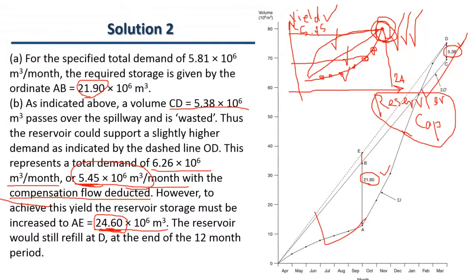On top of all of them, I'd like to give you another level of uncertainty that we have to deal with. That is the uncertainty of the inflow. You're not sure that the inflow that's going to happen is the one that was listed in that figure. Unfortunately, the inflow time series is one of the most uncertain parameters that we have experienced. The rainfall depends on many parameters, as you know better. So uncertainty analysis and its inclusion in this kind of analysis is really key and important.